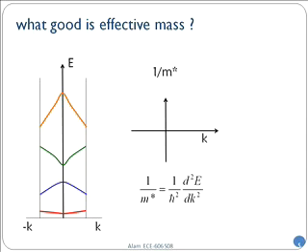Now, one thing I want to point out about this effective mass is that effective mass is not equal to the free electron mass. Effective mass sort of encapsulates the information about the lattice and where the electron is in a given lattice at a given energy. Because the electron, had it been in free space, would always have a value of m naught, 9.1 times 10 to the power minus 31 kilograms, let's say. Of course, in each of these bands, we have already seen the effective mass is variable, sometimes positive, sometimes negative, sometimes 0, all sorts of complicated things, right?